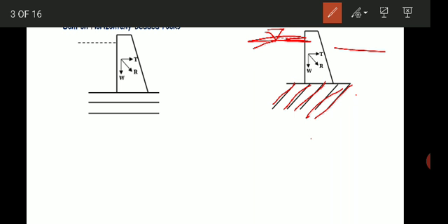Why? Because you can see the resultant of the T and W is acting perpendicular to the bedding planes, right? The bedded rocks are stronger in compression and can bear the stresses when applied normal to the bedding plane.